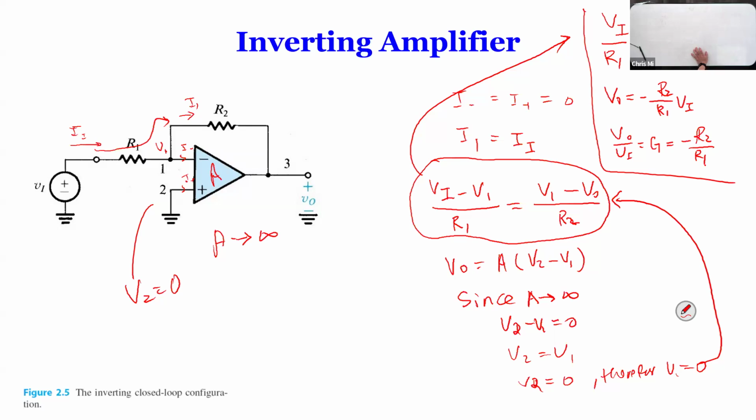Now, of course, that negative, remember, you have to have a negative power supply. If you don't have a negative power supply, your output will be 0 because there's no way you can supply the negative. So this is a very important equation. VO equal to R2 over R1 times VI. So this is called our inverting amplifier with a feedback, ideal op amp.